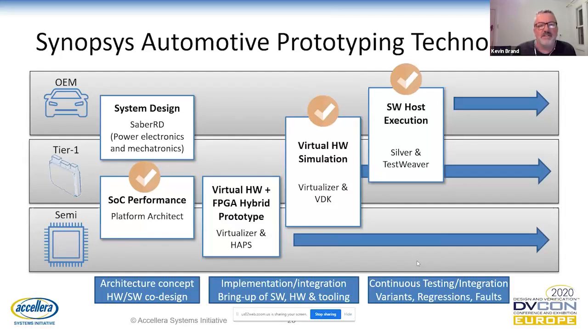So looking more into the software domain, which has been a focus mostly of this presentation, starting with the middle block here, the virtual hardware simulation. This is the Synopsys Virtualizer and the VDK, the Virtualizer Development Kit models. Virtualizer provides the virtual hardware ECU simulations, and they're capable of running compiled software binaries.